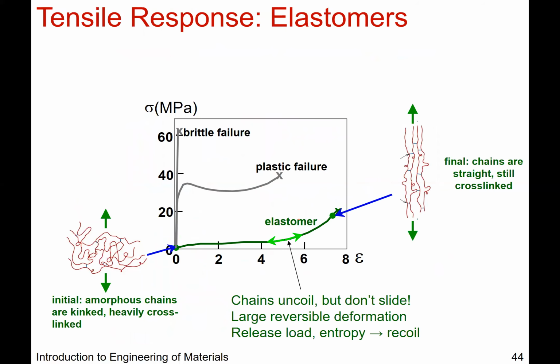And then you have a special class of polymers called elastomers. Interestingly, you can have elastomers that are thermoplastic as well as thermosets. But mechanically, what's happening with elastomers is they start out something like this, there are some amorphous regions, their chains are kind of wonky like this, mostly spaghetti-like is how most people describe it. And then in this region, they start to uncoil and align like so. So they're still cross-linked, it's just now they're elongated and aligned.